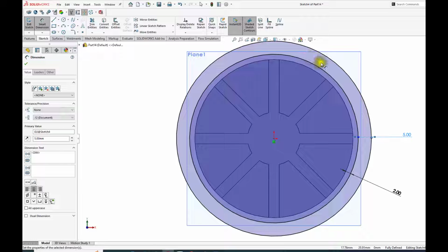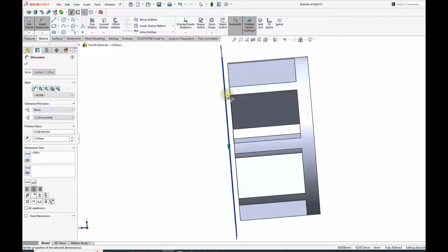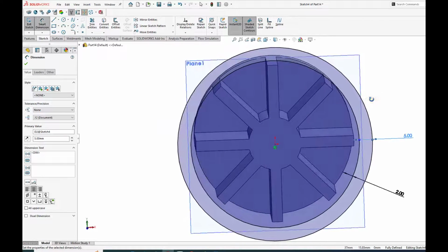Between this circle and this circle is where you're going to construct your casing, starting from a distance of about 2 millimeters from here to here, and probably 2 millimeters down here as well. All right, so that will do. Now what we have to do is complete the extrusion.